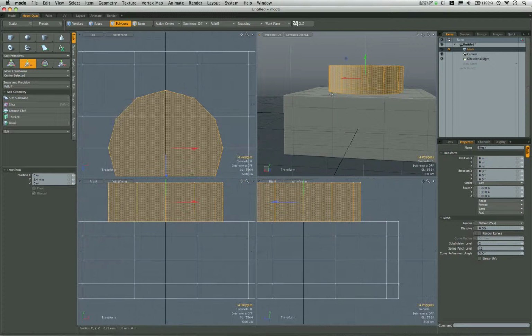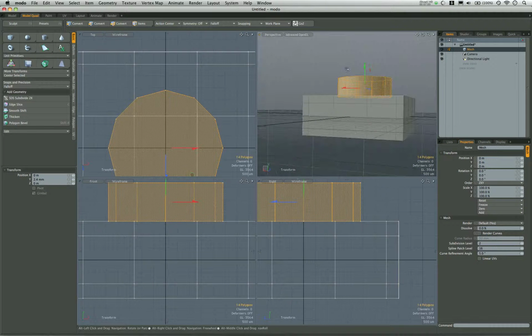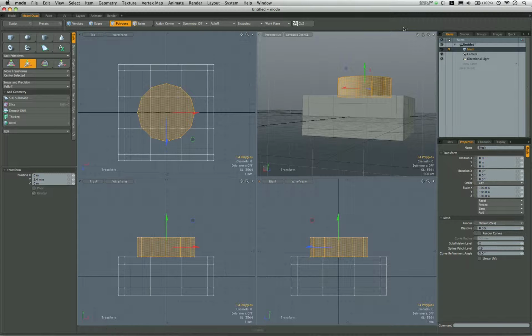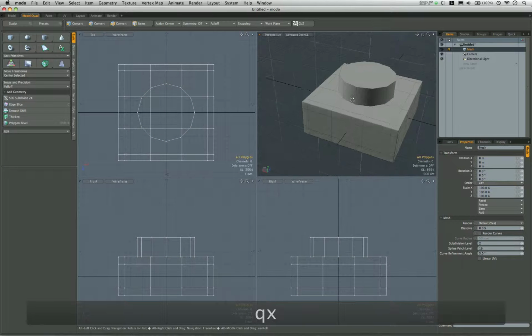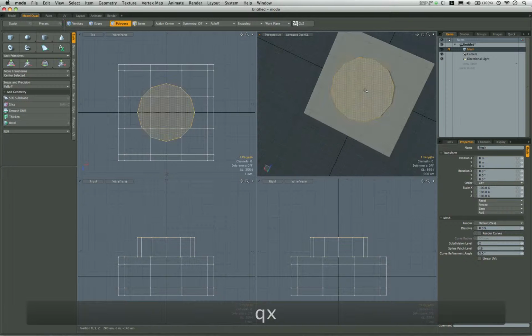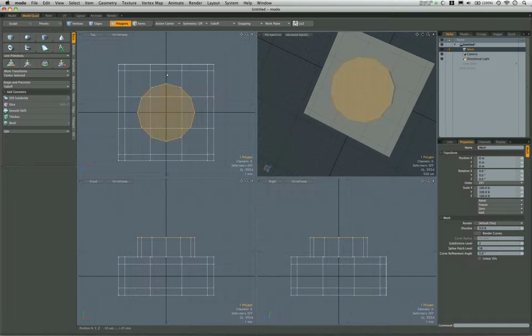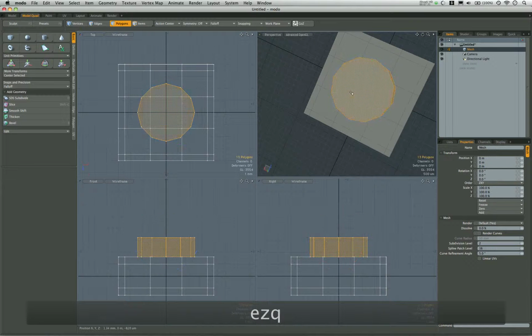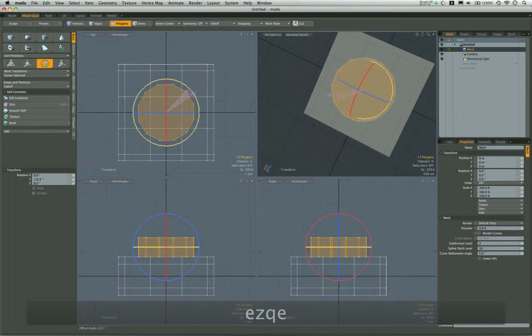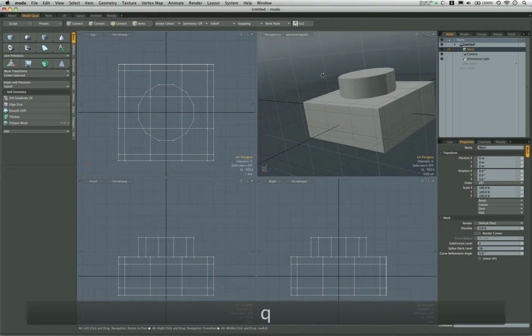That looks right. Okay, and then another thing that we'll notice, well, two things. One is that if we're going to be bridging this to the piece underneath it, we're not going to need the bottom of it. So I'm going to drop my tool here, then deselect the top and the sides, and cut out the bottom. And the other thing is that if we look at the alignment of points here, we can see that we have a middle point here, here, here, and here, whereas the middle on each of these sides of the cube are edges. So we're going to want to rotate this to align edge to edge. So let's select the entire thing, rotate, and it's going to be 15 degrees, either positive or negative, depending on the way you would like to rotate. And with that done, I'm now ready.